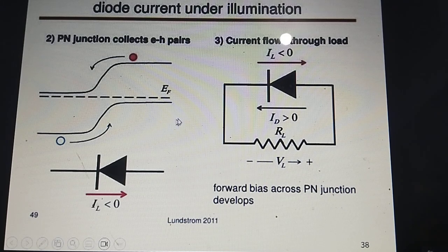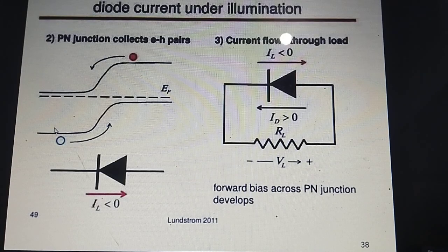So they generate some voltage at the two ends. If we don't apply any contact between p and n, there will be a voltage here. And what if you take a wire and connect the P and N sides with each other? So what will happen? All accumulated carriers will go there, and you will get the highest current, but no voltage.